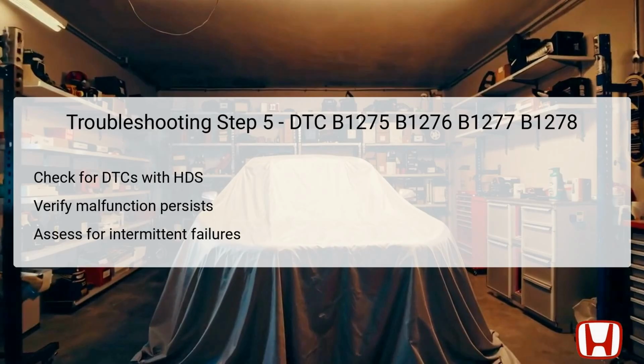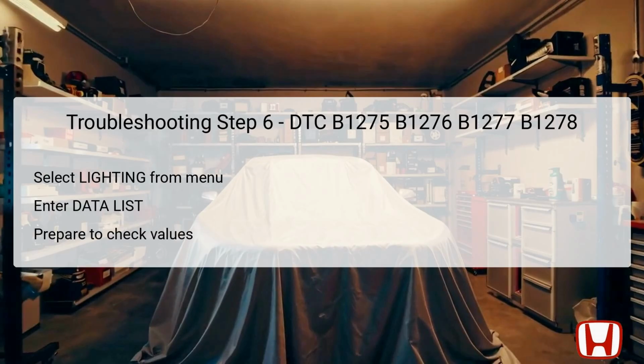This step is crucial in understanding whether the system is genuinely functioning properly or if further diagnostics is warranted. For the 6th troubleshooting step, select the lighting option from the Body Electrical System select menu in the HDS and enter the data list.